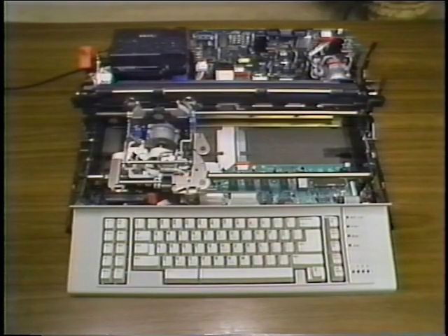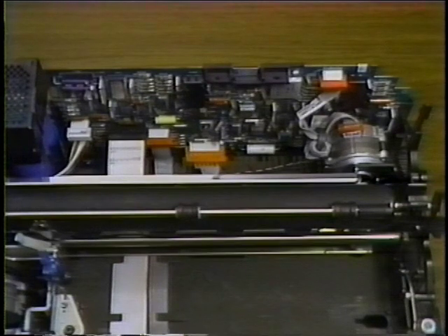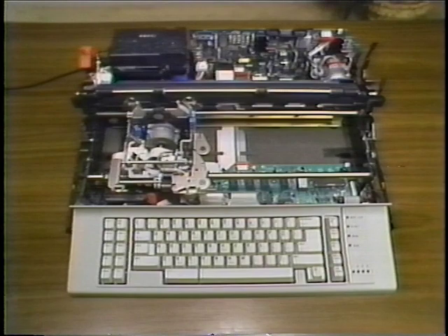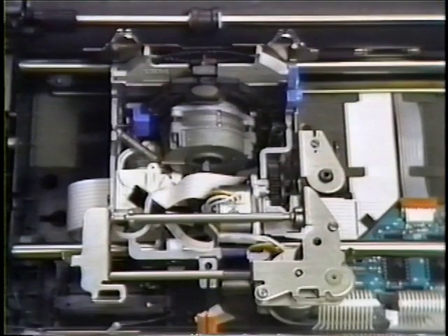The main purpose of the printer board is to provide drive to the stepper motors and the hammer solenoid. The stepper motors turn the platen, move the carrier, feed and lift the ribbon, and turn the print wheel. The printer board also interprets the signals it receives from the homing sensor in the carrier. Character selection and print selects the character to be printed and prints it on the paper. This is controlled by the printer board.